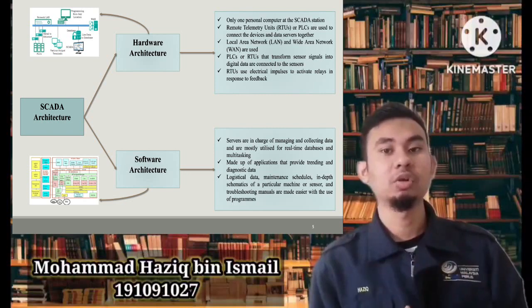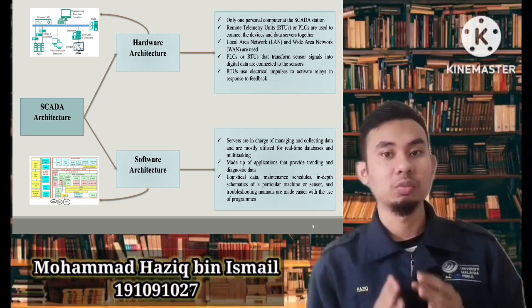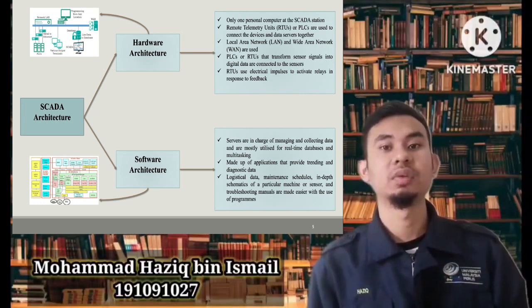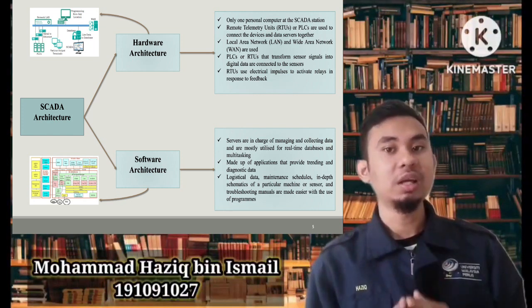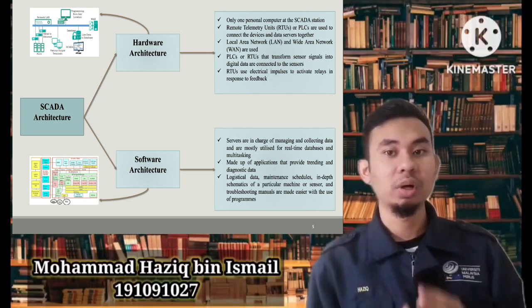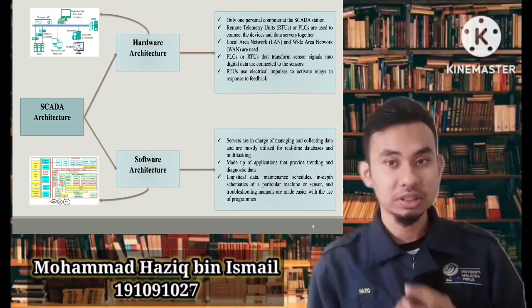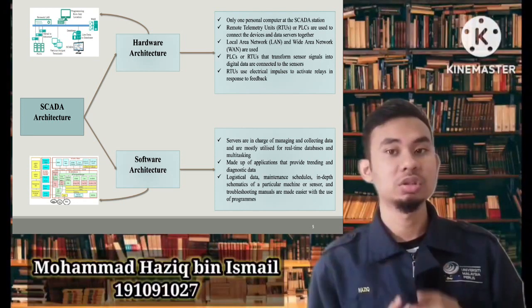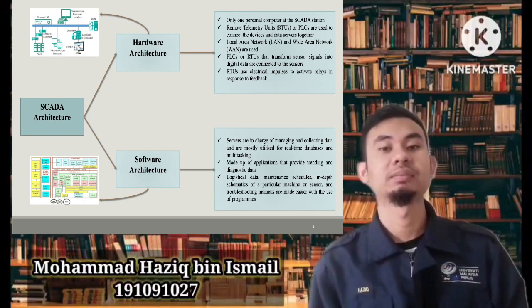There is only one personal computer at the SCADA station. Remote telemetry units, RTUs, or programmable logic controllers, PLC, are used to connect the devices and the data servers together. For communication between devices and the master station in the system, local area network, LAN, and also wide area network, WAN, are used. PLCs or RTUs that transform sensor signals into digital data are connected to the sensors, and RTUs use electrical impulses to activate relays in response to feedback. We can see the figure of hardware architecture at the left side in the slide.